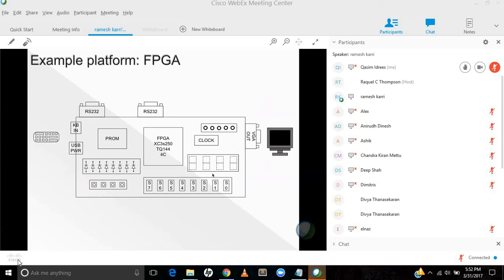So we gave them a design problem: insert a Trojan into AES. We put this AES on the FPGA here, and then connected it through some of these interfaces to display the results and apply inputs through these keys and also RS-232. A couple of students put AES on this, and also designed the interfaces like UART and everything, connected it there, and gave it to the teams.